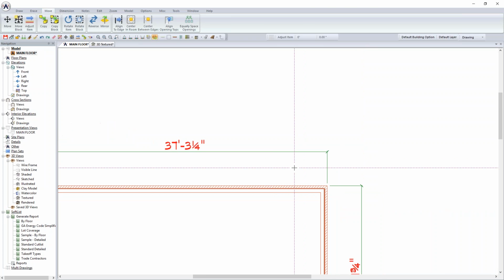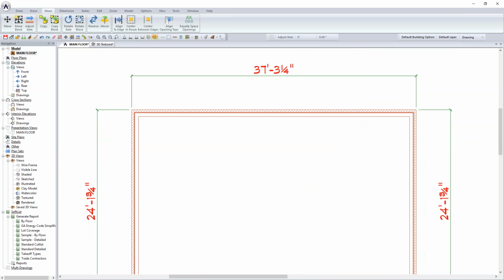Okay, and so I'm going to, as I begin to zoom this out, get it to the largest possible scale. Now, a quick way of zooming your drawing so that it fills the screen, and it is a tool that I will use a lot, is the zoom extent command. So this is an icon I would leave in that toolbar, because I think you're going to reach for it a lot.